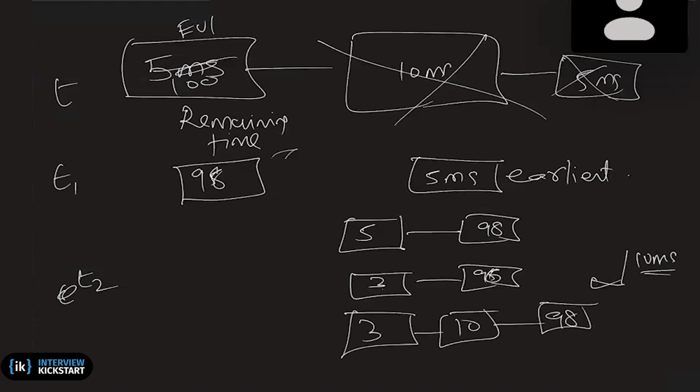Okay. And then when the next tick happens, another delta happens. So let's say three ticks expire at T3. So what you're saying is that you are programming for 5. You are not getting the tick. This is in fixed tick context, right? So you are in the dynamic tick context. You programmed it for 100 ticks. You have not yet decremented this. It is still not firing. It will fire only after 100 milliseconds. Okay, so your timer is still running. The counter is running. Maybe it has decremented by 2, but no ticks have happened.